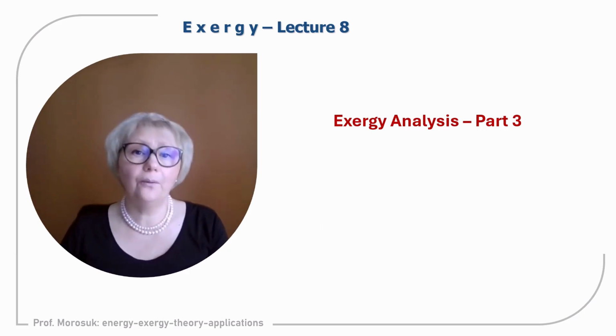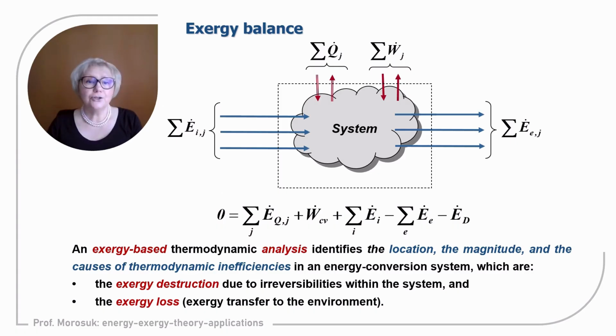Today we continue with the exergy analysis, and today is part 3 of the very big topic, exergy analysis. As usual, I would like to repeat some definitions and statements for each topic, including exergy analysis. So, in exergy analysis, we need to define the location, magnitude, and causes of thermodynamic inefficiencies. And thermodynamic inefficiencies within the system are associated with the exergy destruction term and the term of exergy losses.